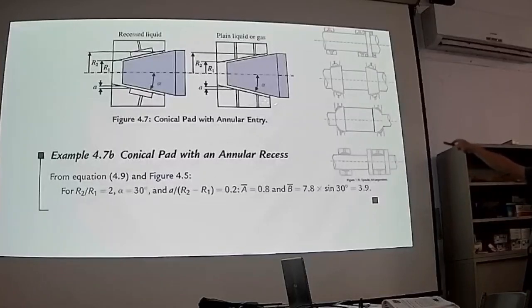So particularly for the air bearing, we prefer this kind of design without recess to avoid the numerical instability. 所以对气压轴承来讲，大部分他们都希望是没有油腔的设计，这样子就不会有气锤的发生，气锤不稳定现象。So this bearing can be used in the spindle, the conical journal bearing spindle in this case.